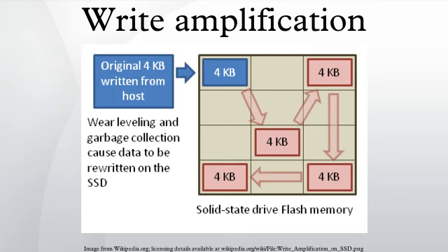Secure erase. The ATA secure erase command is designed to remove all user data from a drive. With an SSD without integrated encryption, this command will put the drive back to its original out-of-box state. This will initially restore its performance to the highest possible level and the best possible write amplification, but as soon as the drive starts garbage collecting again, the performance and write amplification will start returning to the former levels.